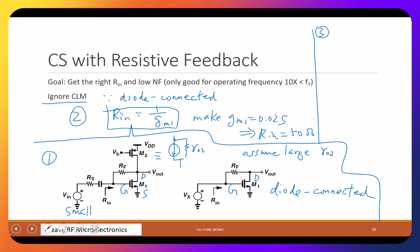In terms of your design, channel length and what else? Length and what? Width. Yeah, very good. So you change the width, change the length, and you change the gate voltage biasing. That's again, if in your design you want to get 50 ohm, do something to achieve this, right? Let me quickly show the diode connector equation, right? Z in of diode connector.